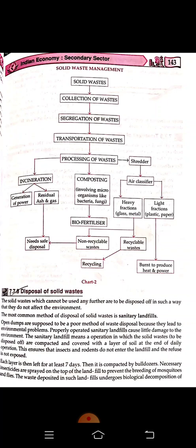The wastewater still contains some organic matter after the primary treatment. So, a secondary treatment of wastewater is needed to oxidize and convert the remaining organic matter to solids that can settle down. At this stage, the wastewater is aerated. That means air is bubbled through the liquid, mixed with bacteria that feed on harmful substances in the sludge. This helps in the decomposition of the organic matter and makes the water less infectious.